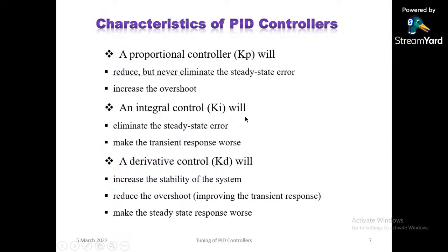Integral controller, read very carefully. The integral controller works the same as, a little bit, a lag compensator. What does a lag compensator do? It improves the steady state response. Same way, the integral controller will also improve the steady state error, the steady state response. Now you can read my first point. My first point about the integral controller: the integral controller will eliminate the steady state error.